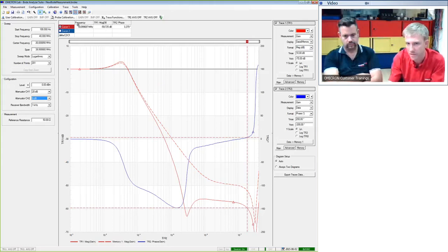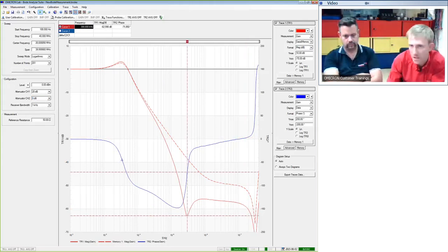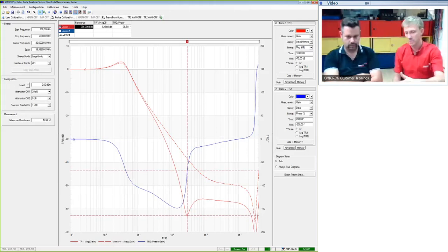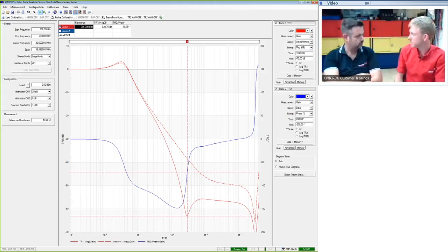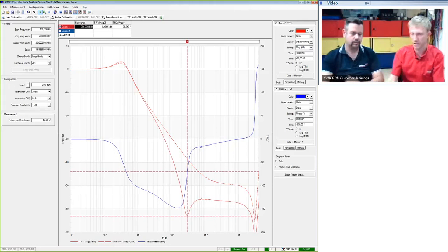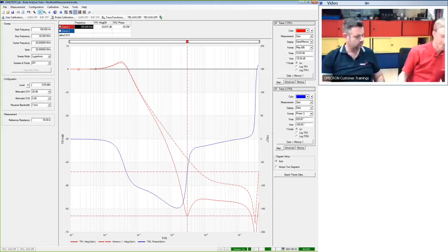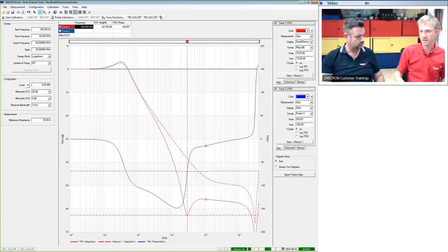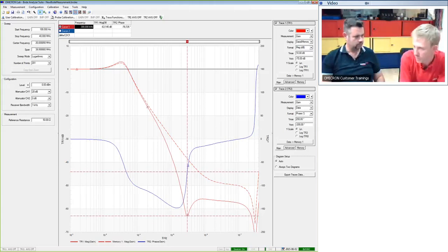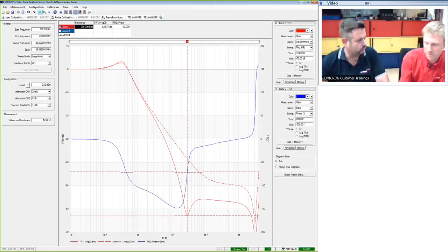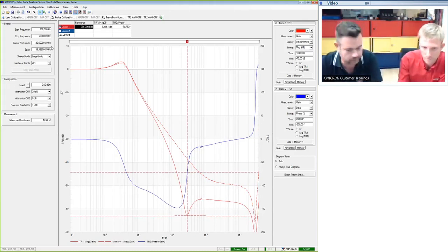So let's assume we have a switching frequency of 300 kilohertz in this converter. Then the attenuation of this filter did improve by more than 20 dB. So you would get a lot less output ripple, and that's due to the fact that the ESR of the ceramic capacitor at that frequency is much lower than the one of the aluminum cap. Now they are in parallel to the aluminum cap, so the smaller capacitor is dominant.